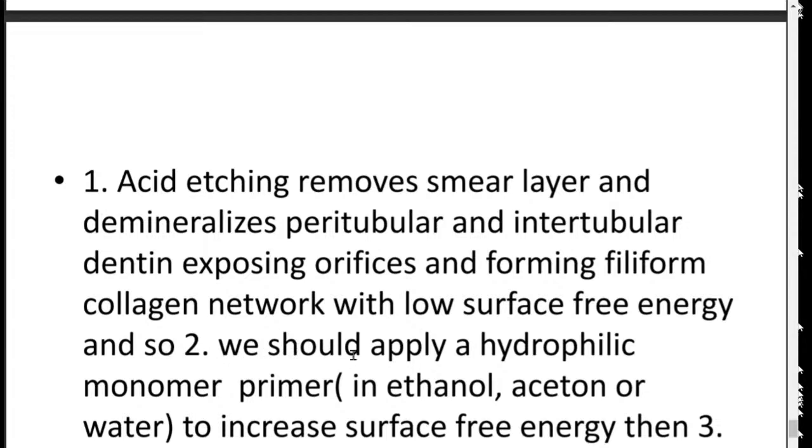The second step, we should apply a hydrophilic monomer primer in ethanol, acetone or water to increase surface free energy.